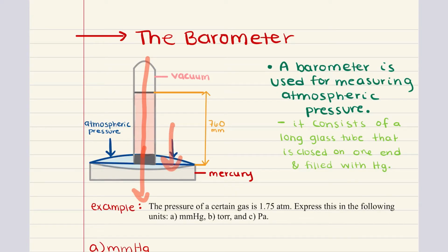All right. If the atmospheric pressure increases, it's going to push more mercury up into the tube. And if the pressure decreases, then the mercury level is going to drop. So it is a balancing force at work here. The height of the mercury column in the tube is going to be measured, usually in millimeters, and the height corresponds to the atmospheric pressure. All right, so these are the 2 instruments that we're going to cover here.